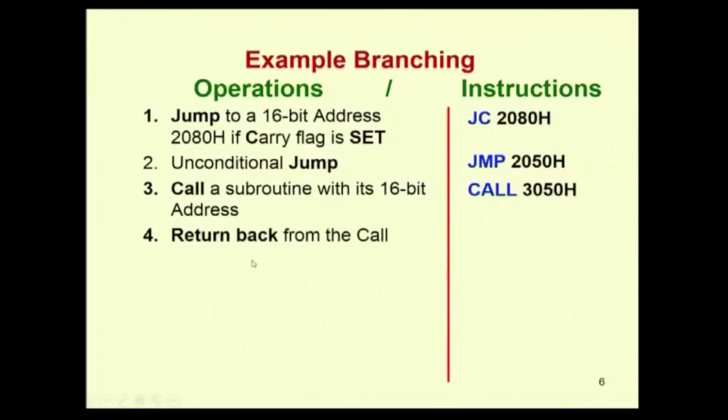And another is of course coming back. The call instruction is always associated with a subroutine. It will go to a subprogram, and once it has finished the subprogram, it has to return back to where it left the original program. The microprocessor will remember, using the stack pointer, where it has left.